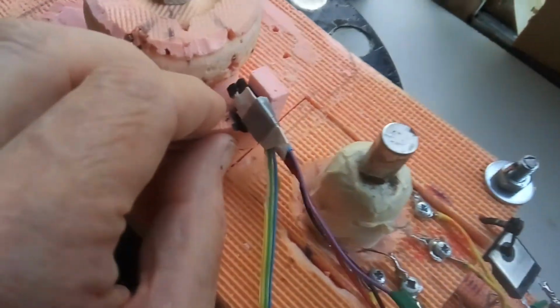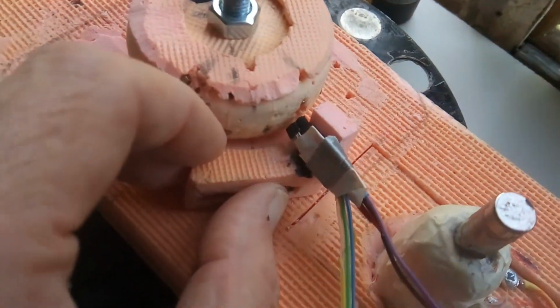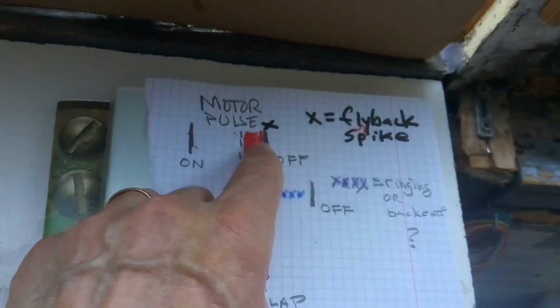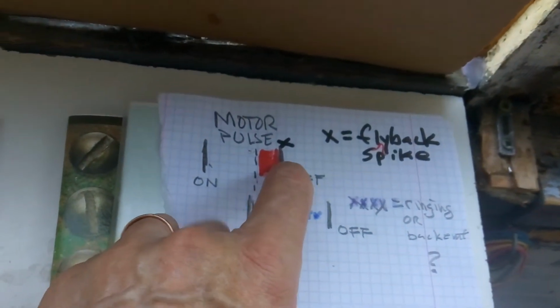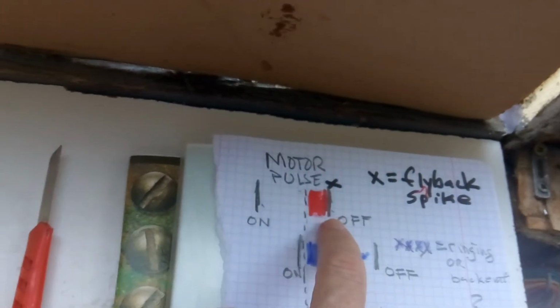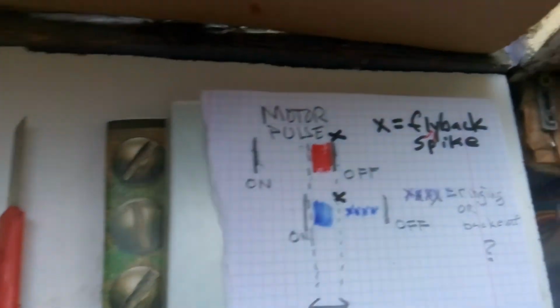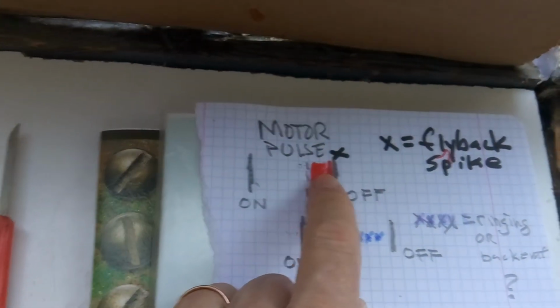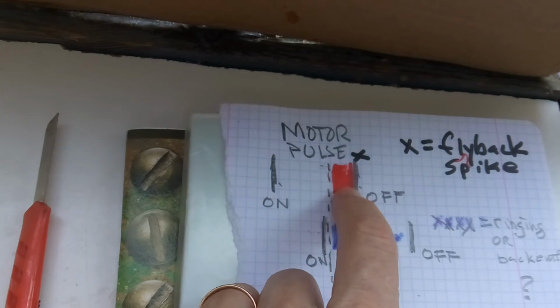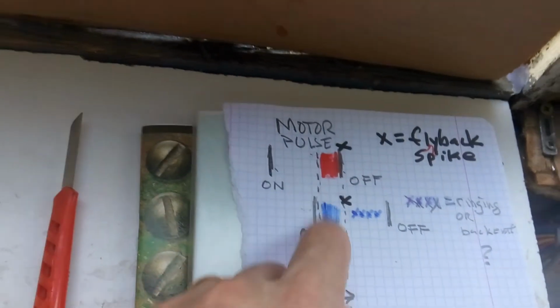Okay, the advantage of this is when you fill up large capacitors without doing this, just like doing a motor coil pulse, have a steering diode coming off the drain of the MOSFET, and filling up capacitors continually all the time during the motor coil pulse, which is kind of the normal way to do it.